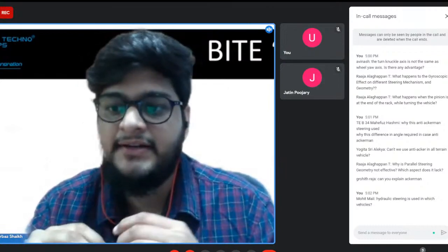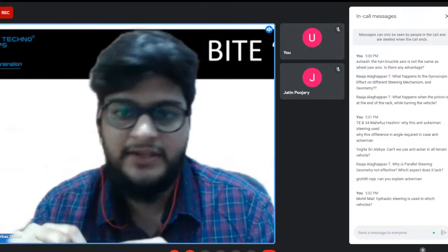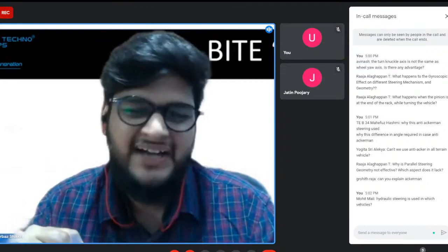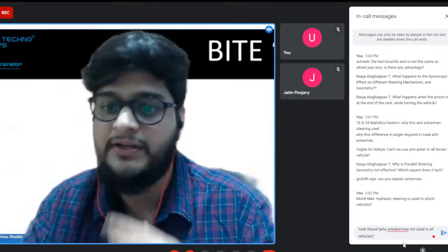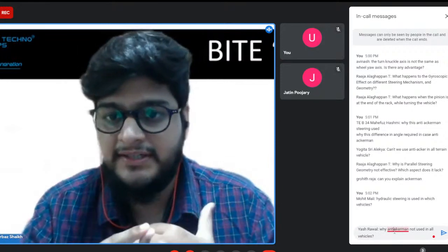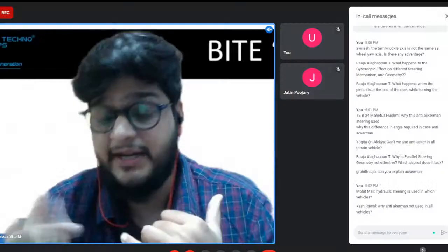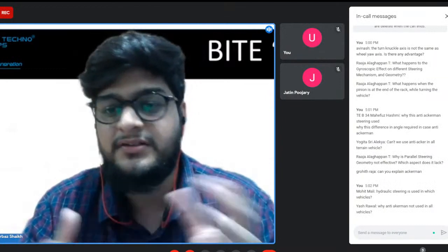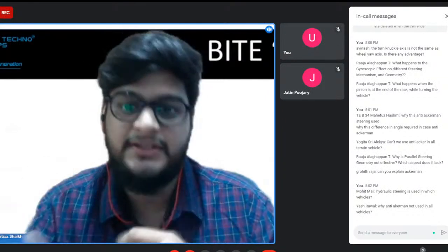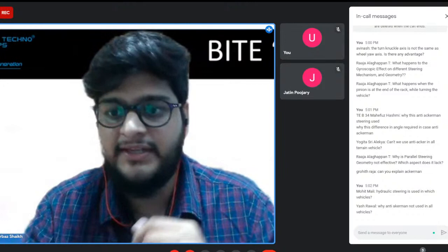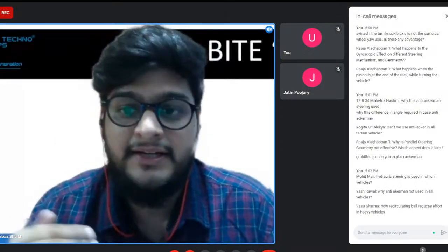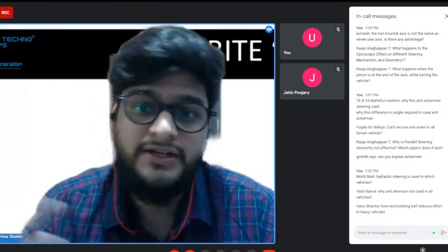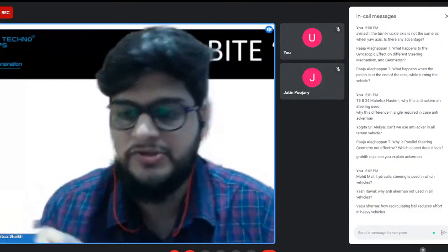Okay, Yogita is asking, can't we use anti-Ackerman in all terrain vehicles? You can, but I don't think it will be very efficient, because if you go with Ackerman geometry, that has its own advantage. The tires' wear and tear will be less. It will be easier to calculate your turning radius and all those things when you're making an ATV. If you use anti-Ackerman geometry in an ATV, the problem will be that the ATV does not go at a higher speed that it is supposed to generate enough grip in the anti-Ackerman geometry.